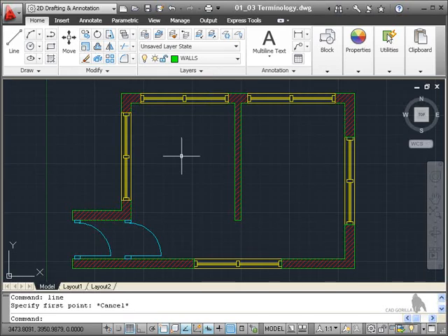What other terminology do you need to know about? Well, right down here at the bottom of the screen, we have the status bar. That shows you your drawing coordinates. AutoCAD is a coordinate-driven product, and these icons here are your drafting settings. So you've got things like ortho mode, you've got things like object snap, 3D object snap, object snap tracking.